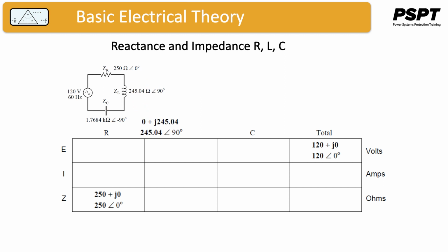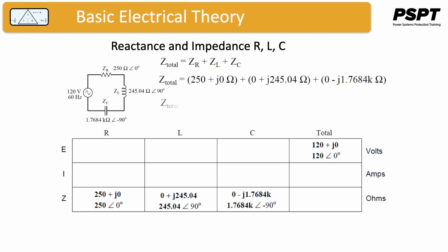Notice that we are assuming a perfectly reactive inductor and capacitor with impedance phase angles of exactly plus 90 and minus 90 degrees respectively. Although real components won't be perfect in this regard, they should be fairly close. For simplicity, we'll assume perfectly reactive inductors and capacitors from now on in my example calculations, except where noted otherwise.